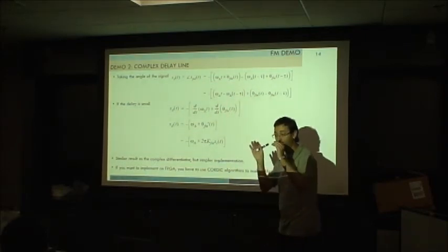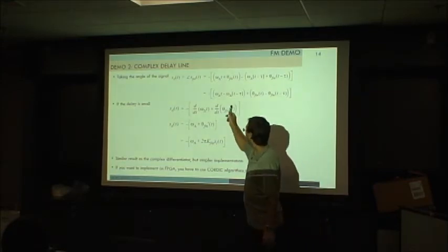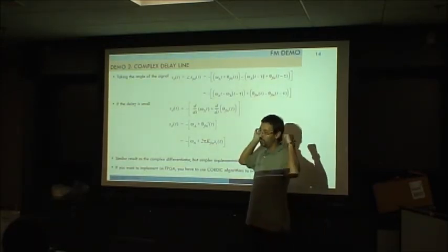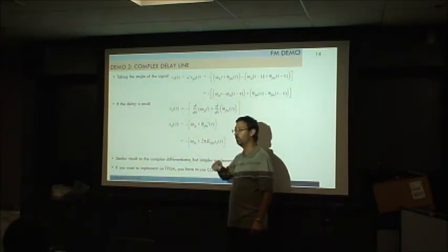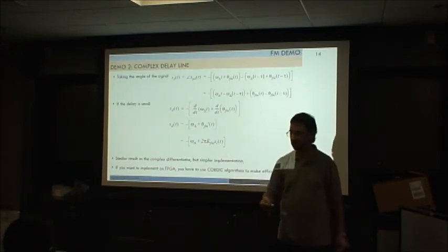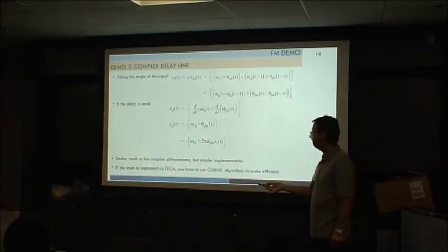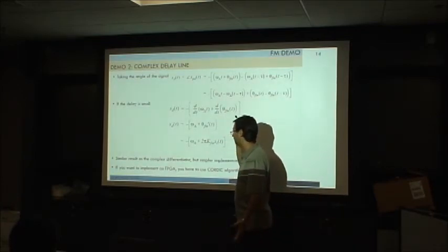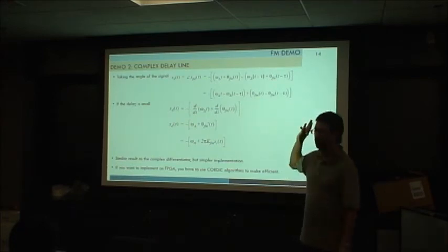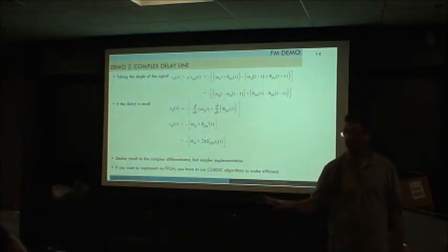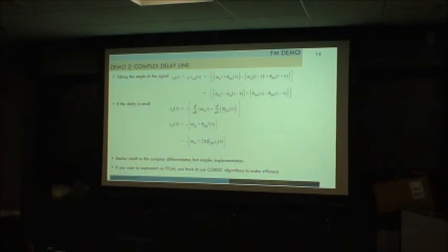And the same on this, if the phase difference is really small, it will approximate to some derivative stuff. If you remember, the differentiation result was this one. Exactly the same. So we arrive at the same result, but much easier in hardware implementation. So we take the derivative of this and we will recover our signal. But this one is the one that we will implement on the SDR. The other not, because it takes more. Anyways, nobody implements it that way. It's just to give you an idea where the theory came from.